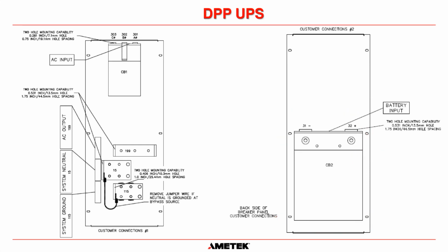And if you close that breaker, what's going to happen is there's a fuse inside our system and there's a reverse polarity diode usually, and that fuse is going to blow and you won't be able to start up your system correctly. So it's very important to make sure your electrical contractor knows what they're doing when they're connecting the battery to the UPS system.